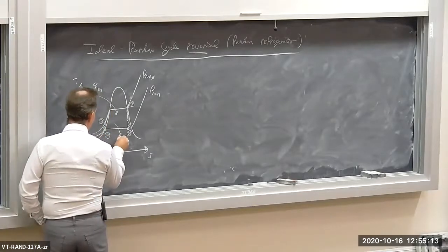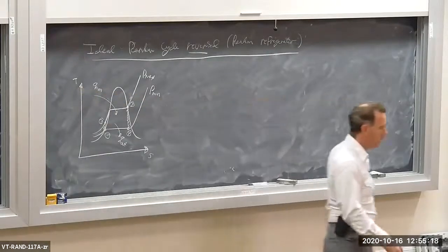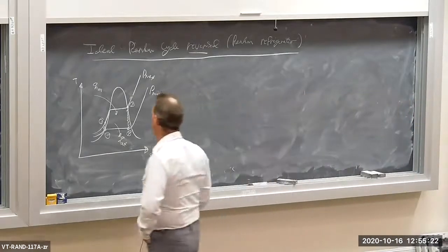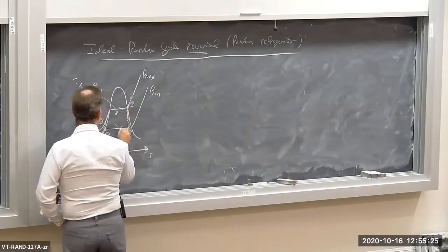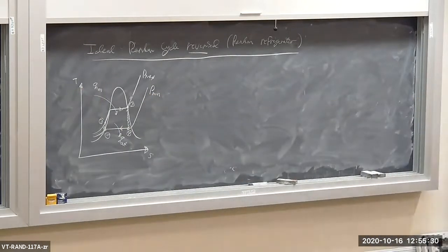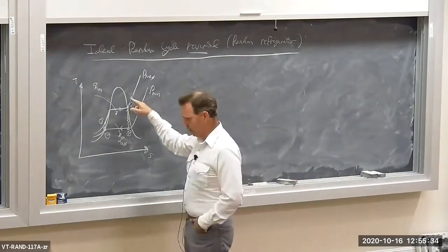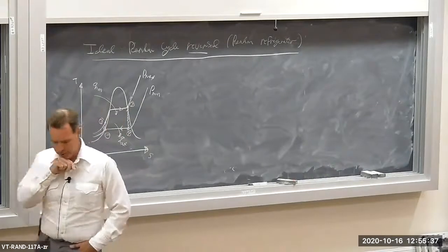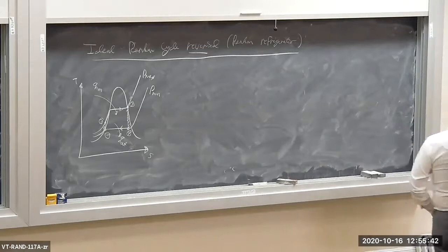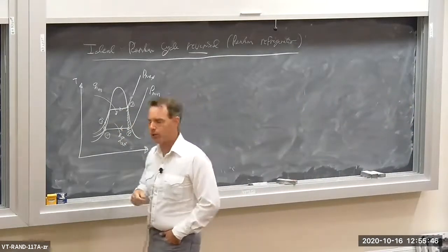And then we reject the waste heat in the condenser. So Q out occurs from 4 to 1. Okay? And the cycle, of course, moves in the clockwise direction. So this is the ideal Rankine cycle. In the examples that we've done, superheated vapor for state 3. So we have superheat, and then we have non-ideal pumps and compressors. So these wouldn't be isentropic compression and expansion processes.